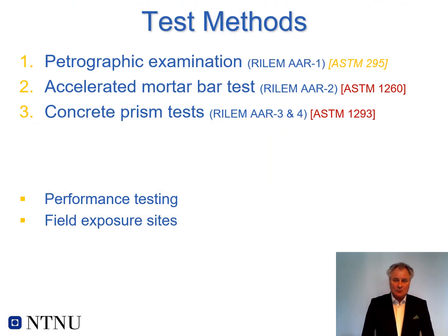The main outcome of this work has been that we have developed this RILEM test method, a three-step test procedure, starting with a petrographic examination. In this petrographic examination, which is called the AAR-1 method, you look in a microscope to see what kind of aggregates you have, whether you think it's reactive or not, and so on.